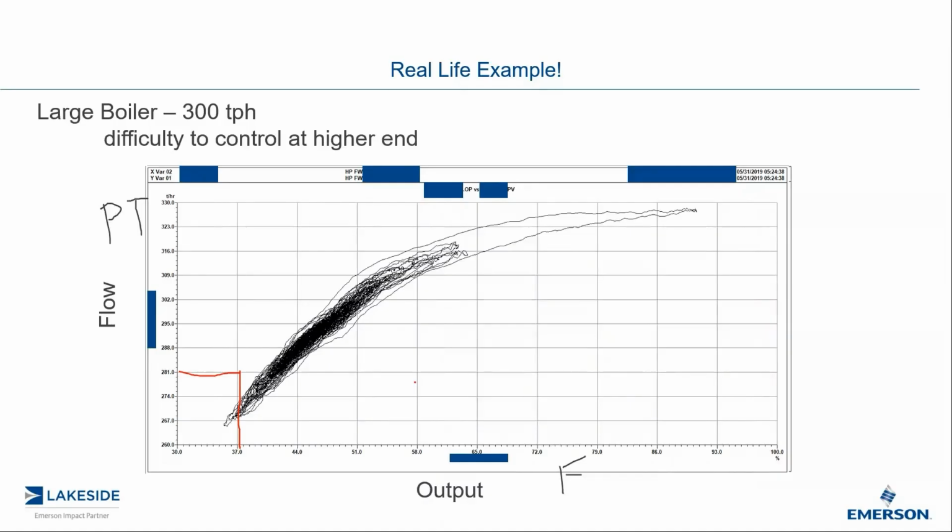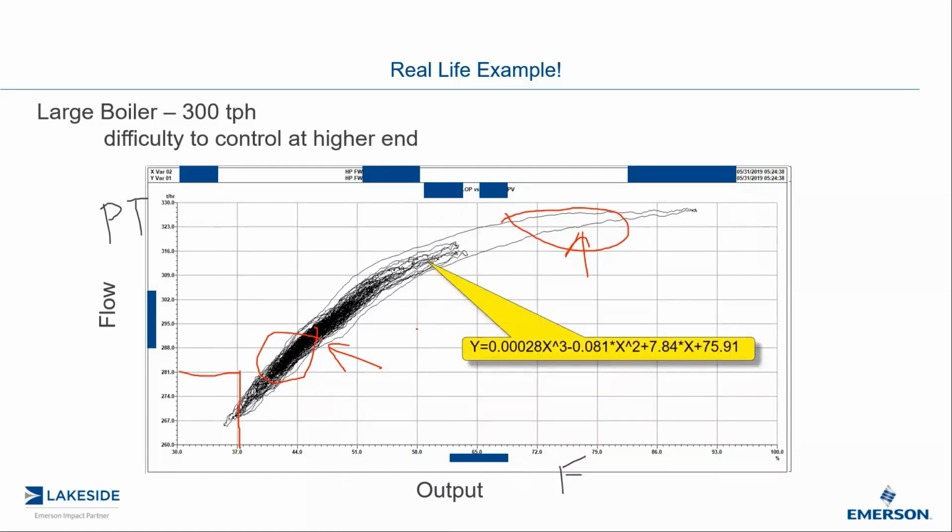And so obviously we know with the boiler feed water, we have a feed water flow controller. We could tune it down here, but the response, if it's operating up here, which is where they operate a lot of the time, would be very slow. And therefore that would cause a drum level swing. Again, I could tune it up here, but at low loads, it would be unstable. And so therefore I had to implement a characterizer, not because the valve was actually nonlinear, because the pump itself was unable to supply the flow at the top end.